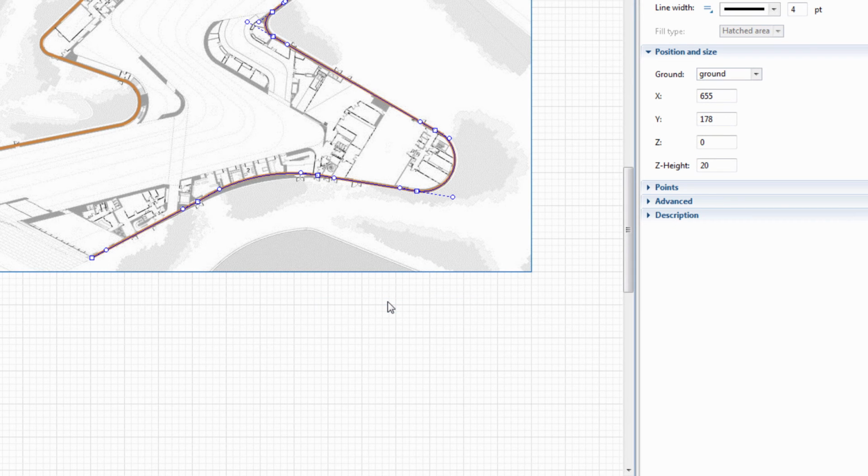Notice the 2 guiding lines that appear on the sides of each wall point. You're probably familiar with them from any other graphical editing software that deals with Bezier curves. Drag the markers at each end of the guiding lines to adjust the curvature of the segment.